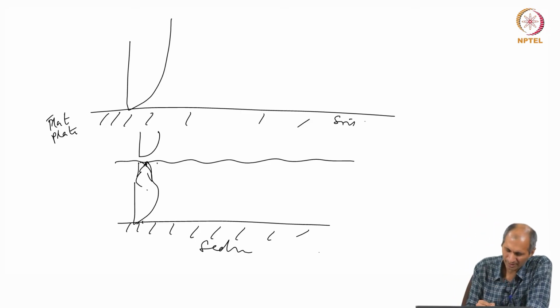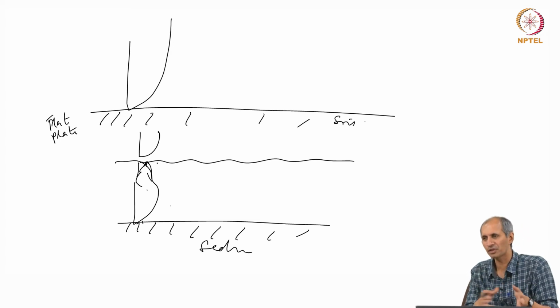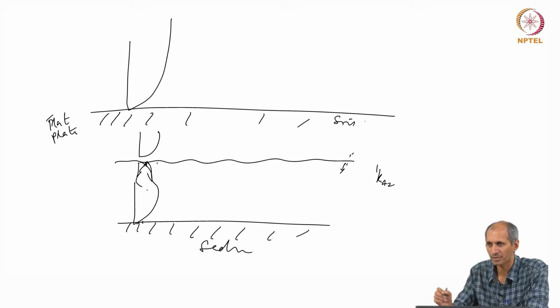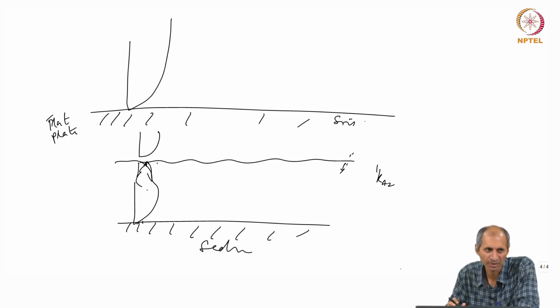So, the correlation may not exactly be the same as flat plate, but if you do not have anything else, you can use this. Fortunately, there are correlations for streams, water side coefficients, so you can use that. The only place where you do not have enough correlations is the water side coefficients for streams at the air water interface. There are very few correlations, as you will see, for this Ka21 for streams. Then you have to use whatever is available, like the ones we saw at the beginning of this class. It is a bad correlation, but that is the only thing available, you just have to use it, there is nothing else you can do.